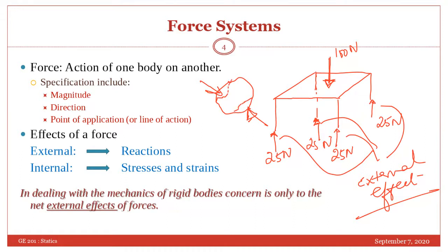And because of this deformation, as you know, deformation will produce the strain. Strain is what? Deformation per unit length, for example, in the linear body. Okay, and then this strain will produce a stress. And from Hooke's law for an elastic body, the stress is proportional to strain, and stress upon strain is a constant, which is called the modulus of elasticity.